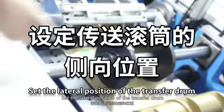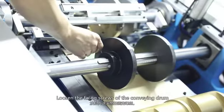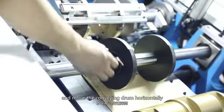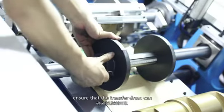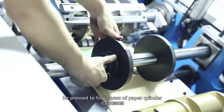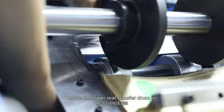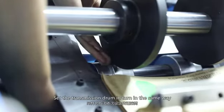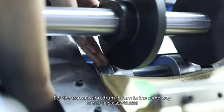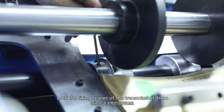Set the lateral position of the transfer drum. Loosen the fixing screws of the conveying drum and move the conveying drum horizontally. Ensure that the transfer drum can be pressed to 4 layers of paper cylinder. Move the lower seat transfer drum to align with the upper seat transfer drum. Set the transmission drum in turn in the same way. Lock the fixing screws of the transmission drum.